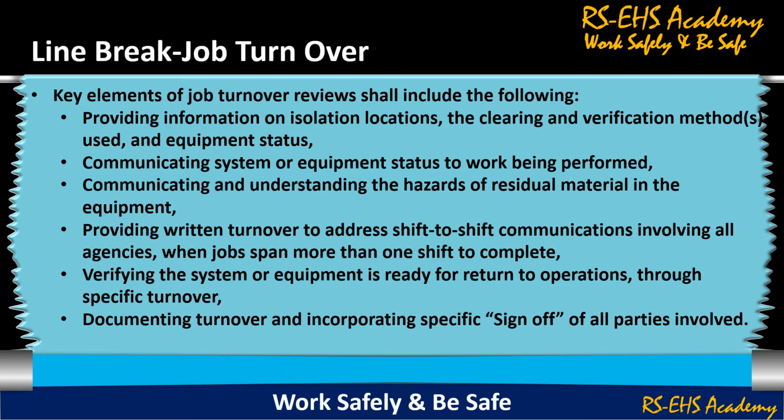Providing written turnover to address shift-to-shift communication involving all agencies when jobs span more than one shift to complete. Verifying the system or equipment is ready for return to operations through specific turnover. Documenting turnover and incorporating specific sign-off of all parties involved.